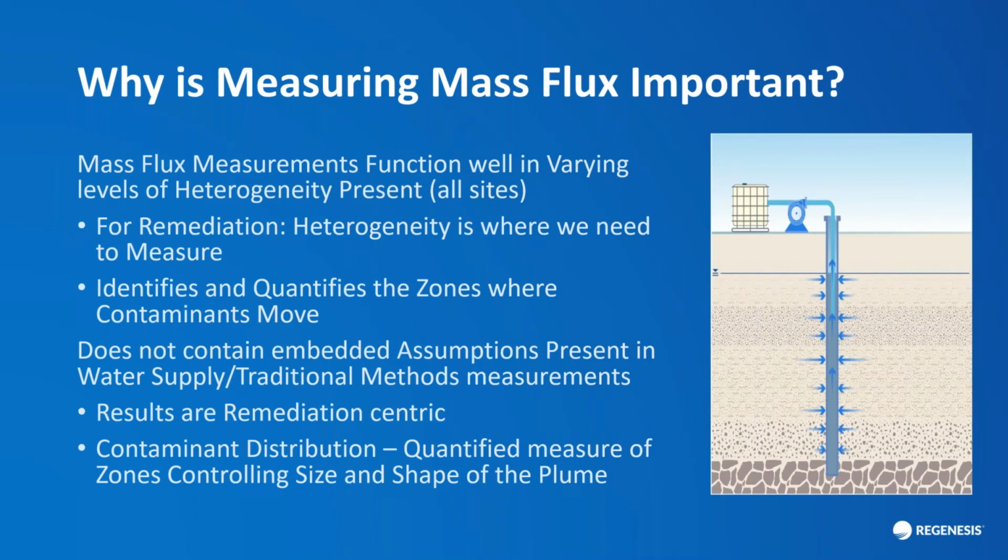Mass flux measurements function well in varying levels of heterogeneity that are present. And folks, heterogeneity is present at all sites. I don't care how clean you think your sand is, you have subtle differences in hydraulic conductivity that change the velocities, and so the mass flux. For remediation, heterogeneity is where we need to measure. It's where the action is, folks. So it helps us identify and quantify the zones where contaminants move.